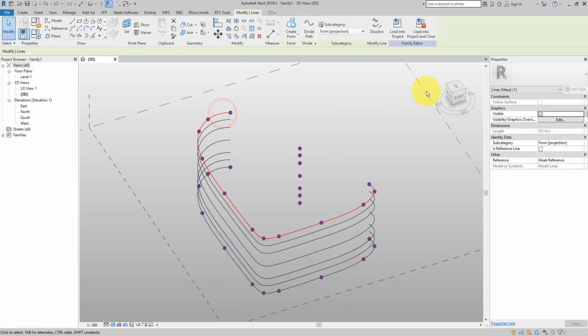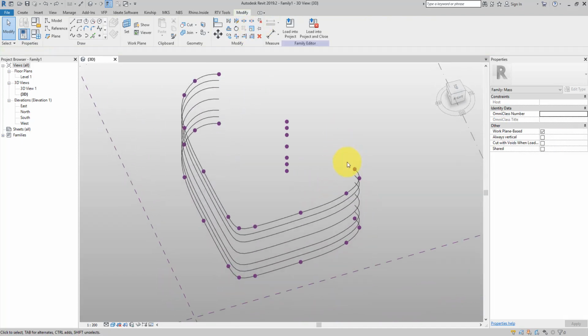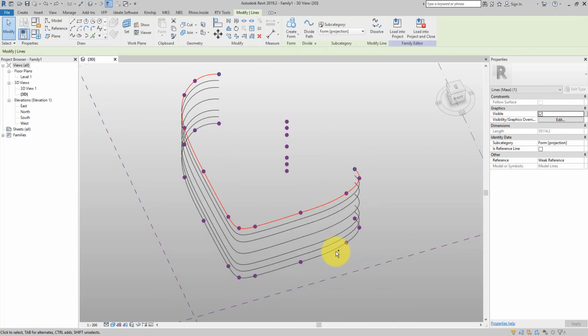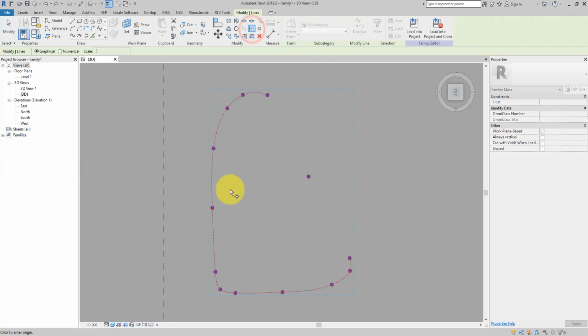When I now click on this line there, go to top view, I can see it's now scalable for me. Let's not forget to get this line at the bottom as well, and then go to top view, and then use this scale button here to scale them around this center point we have from before. Click once, and then make them smaller like this.